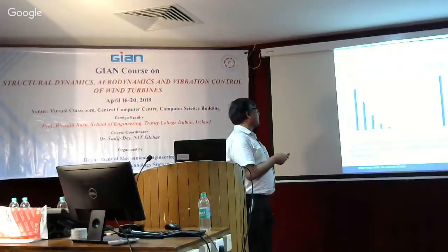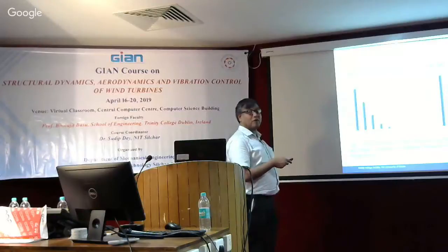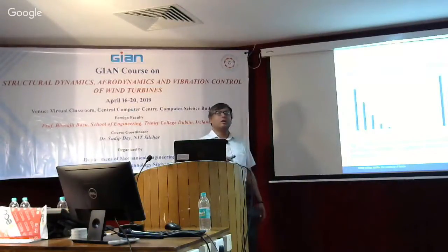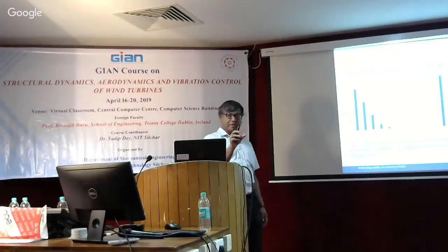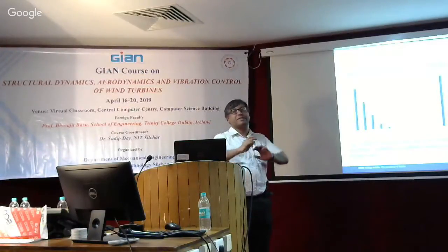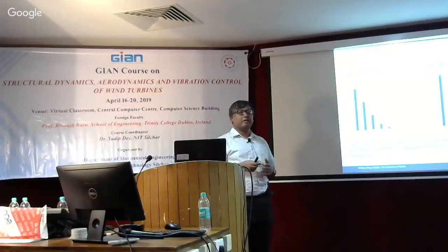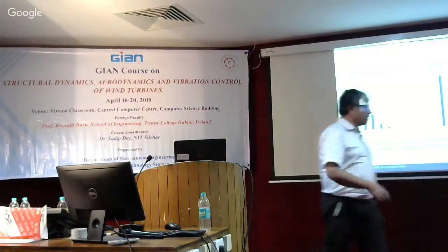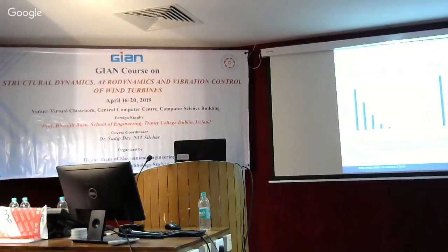And obviously, if you have higher control effort, which corresponds to a lower value of gamma, so this gamma is actually the weight that we put on the control effort. If it's very low, then we want to optimize the response irrespective of whatever control force is needed. So we have two quantities to see, if you recall the integral we had.